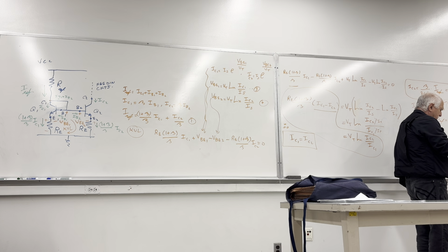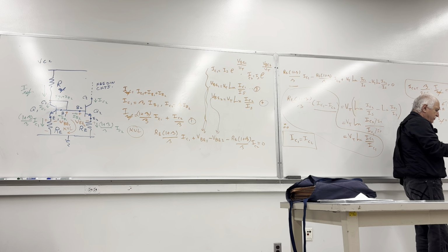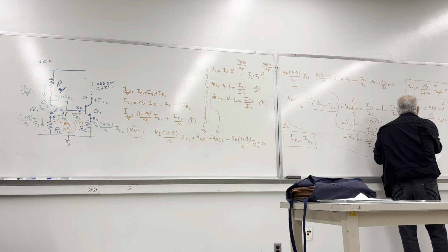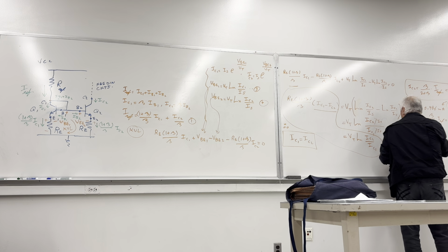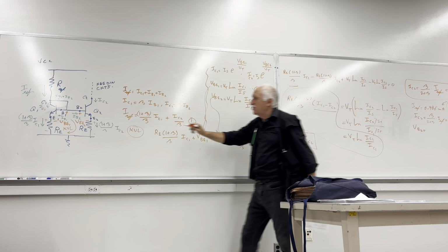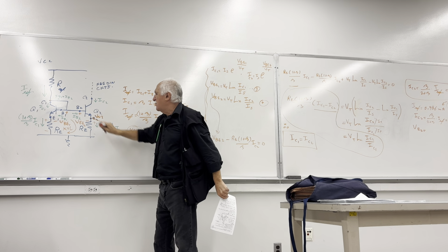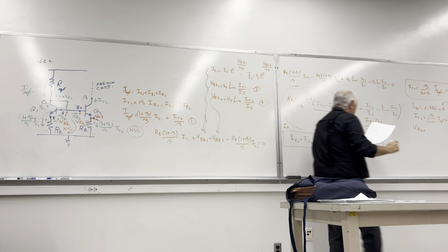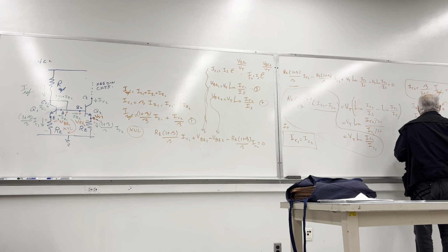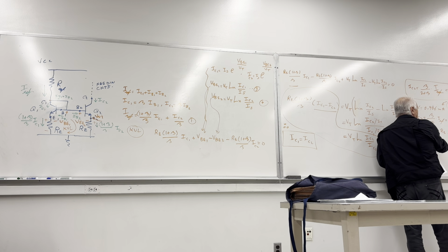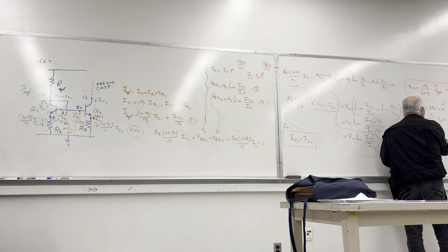So we got those. Then VE2, the voltage in here, right there. How much is that emitter voltage? That is equal to IE2 multiplied by RE. So that is equal to, instead of that, we will substitute (1 plus beta) over beta times IC2.